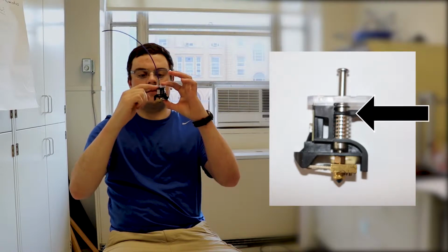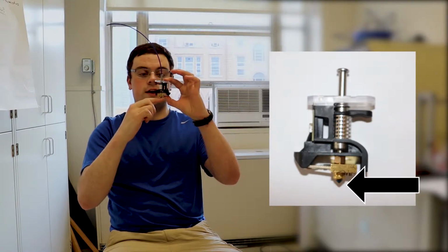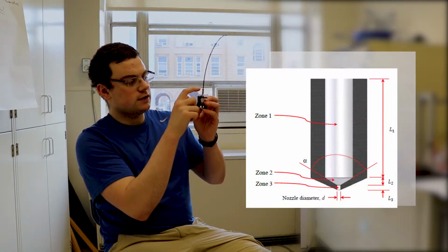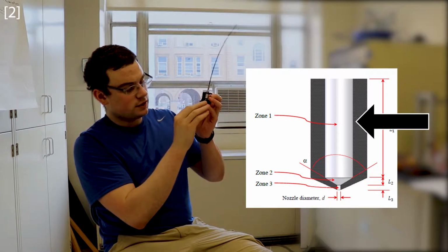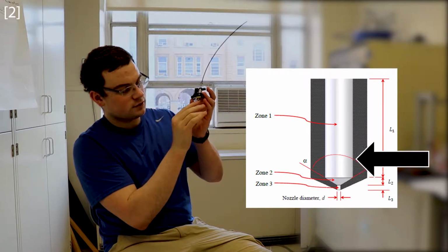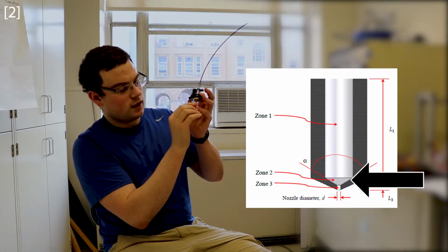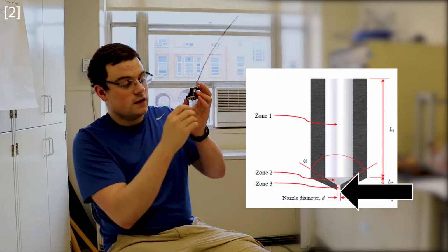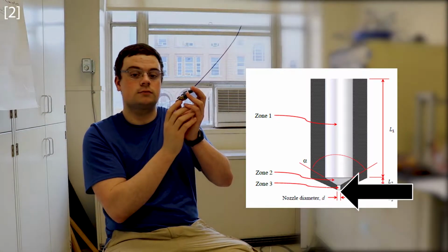In this first section of your print core, this is your cold end from here to here. Then from here to here is your hot end. There are 3 pressure zones in a print core. The first one is the largest one, from the tip where the filament enters until right before the nozzle begins to angle down. The second section is where the nozzle begins to angle down at a 120-degree angle. And the last pressure zone is at the tip where it meets atmospheric pressure.